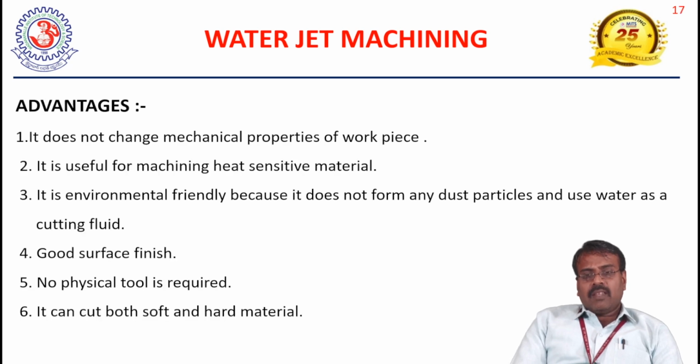Next, what are the major advantages of this water jet machining? It does not change the mechanical properties of the workpiece, as I told you earlier. It is useful for machining heat sensitive material. It is environmentally friendly, called eco-friendly because it does not form any dust particles and uses water as the cutting fluid. And once the water is used, we can recirculate it, and after some filtering process, we can reuse it also.